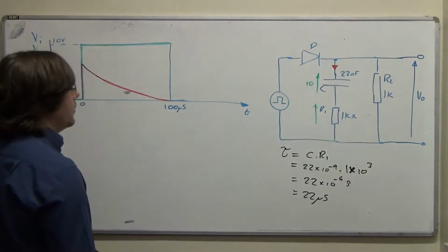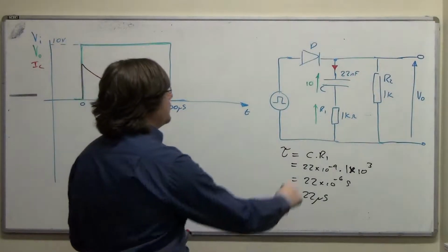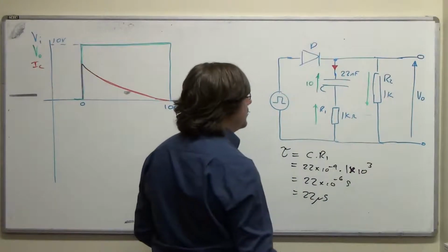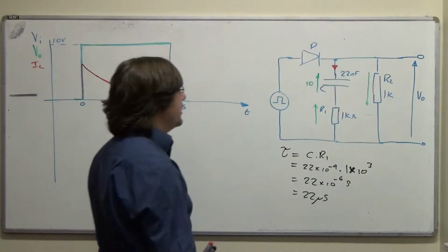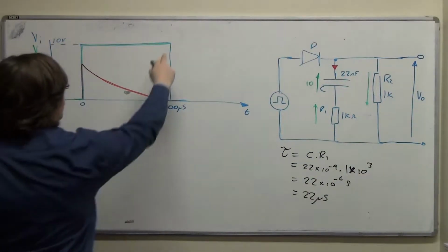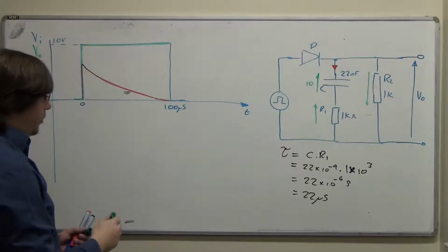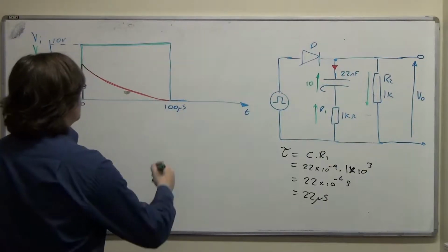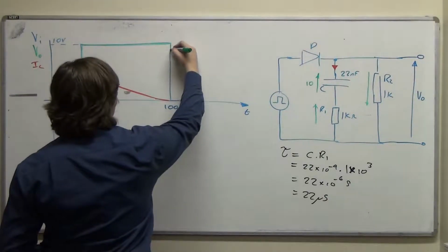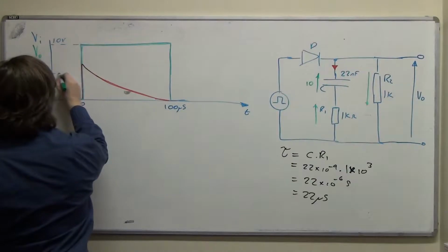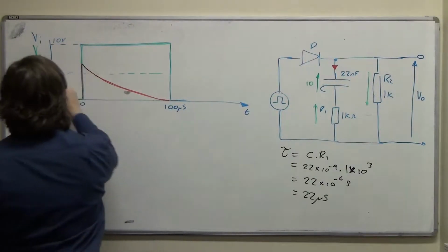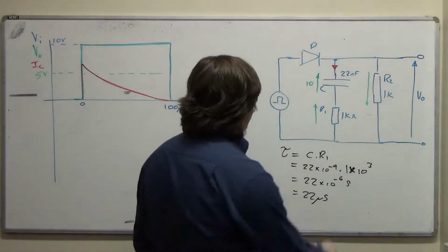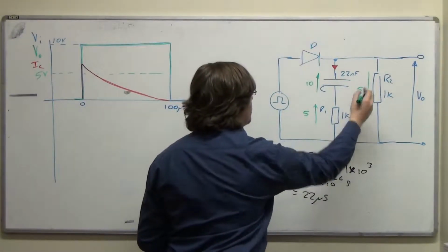The only problem is, of course, that 10 volts looking this way ought to produce 10 volts looking that way. So actually we'll expect a drop from here downwards by half of the value that C is charged up to. So the very next thing that happens is this will drop down to 5 volts. So we end up with 5 across there and 5 across there.